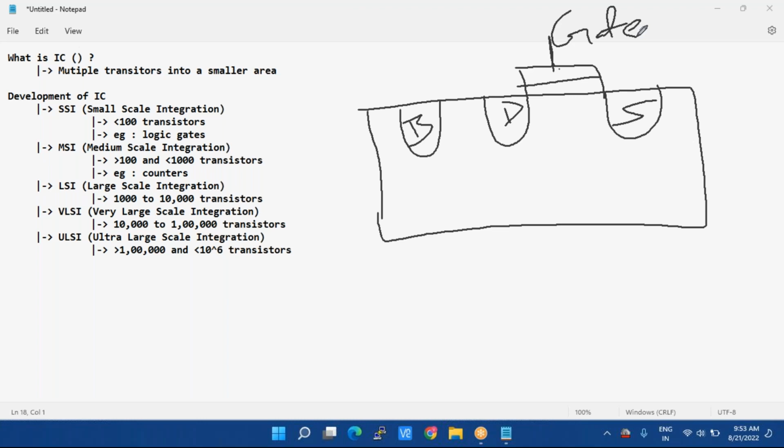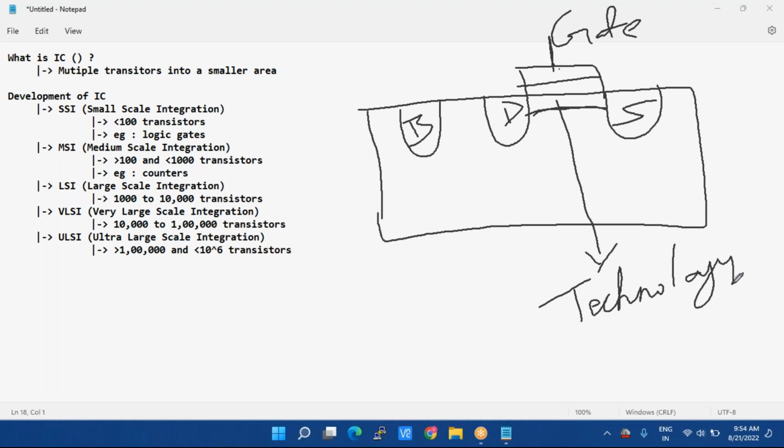Yes, so by the channel length, we mean the distance between drain and source, right? Yeah. So the distance between this drain and source is what gives the term technology node, in which you have said a few terms: 180 nanometer, 90 nanometer, 7 nm. All of these are telling the distance between this drain and source only.